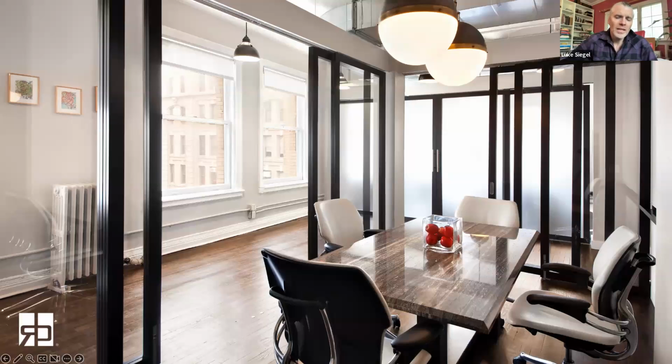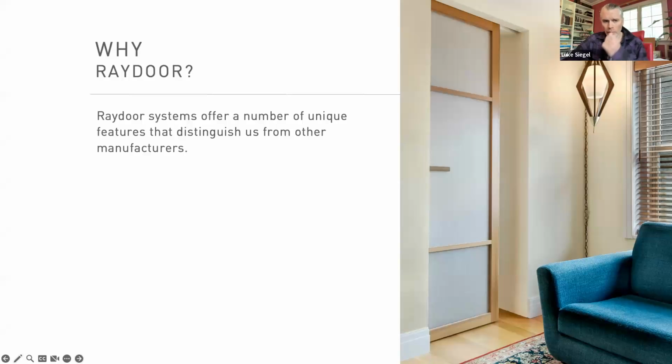And this slide here, I like to just showcase again, you could see that thin soffit where the HVAC system is running above the door system in the foreground. It's just a reminder that our panel is going to weigh something in the area of 70 to 120 pounds. No matter how large our panels are, they're generally much lighter than glass. So for instance, our largest panel size is 5 foot wide and 10 foot tall, and that's going to generally be in the area of 100 to 120 pounds in weight. So it's very versatile from that standpoint.